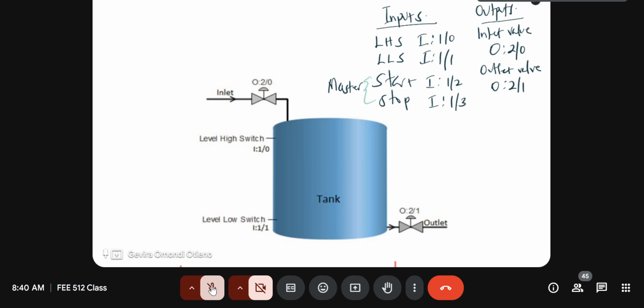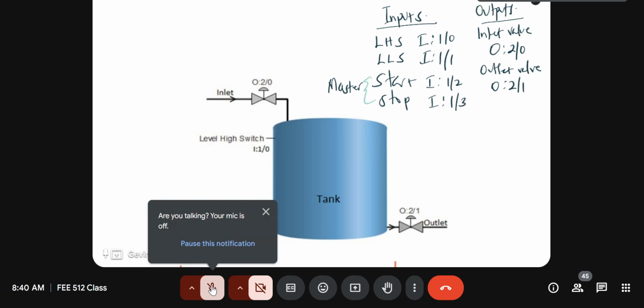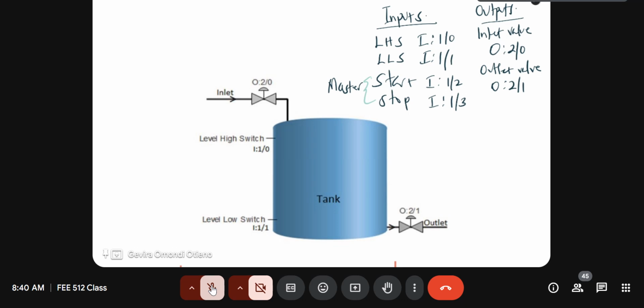Okay. Now, again, we expect that when I start, I don't want to start and then the water starts flowing and then I stop. So it means latching is important here as well, so that when you press the start button, the thing can work on its own up until the time you press the stop button. Yeah, so again, it's important to remember that you expect that the control valve here would be latched so that you have a continuous fill or emptying, because the process has to be automated. You can't be there to open the valves and close the valves. That's a manual way of doing it. So all I have to do is press a start button or press a stop button.